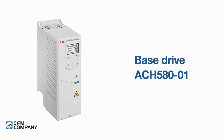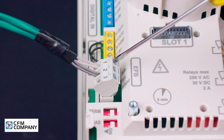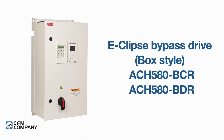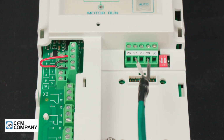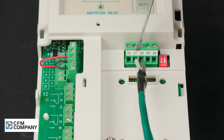Depending on the model of ACH580 drive, the serial communications wires are landed at different locations. For drives without an Eclipse bypass, such as a base drive or a drive with a package disconnect, the wires for serial communications are landed on the EFB terminals of the drive. For drives that include an Eclipse bypass, such as a box-style enclosure or a vertical-style enclosure, the wires for serial communications are landed on the horizontal terminal strip of the bypass control unit, RBCU.